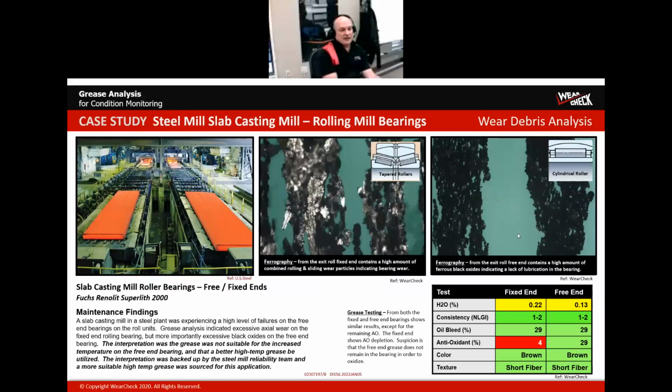If they form a very small oxide layer, or don't form an oxide layer, then the particle will remain shiny. But as the oxide layer thickens, the wavelength of light that's being transmitted back or absorbed, and the apparent color, is a longer wavelength light. Obviously blue is a longer wavelength. So when we see blues, we know it's a deeper oxide layer, which means it's lower alloy.